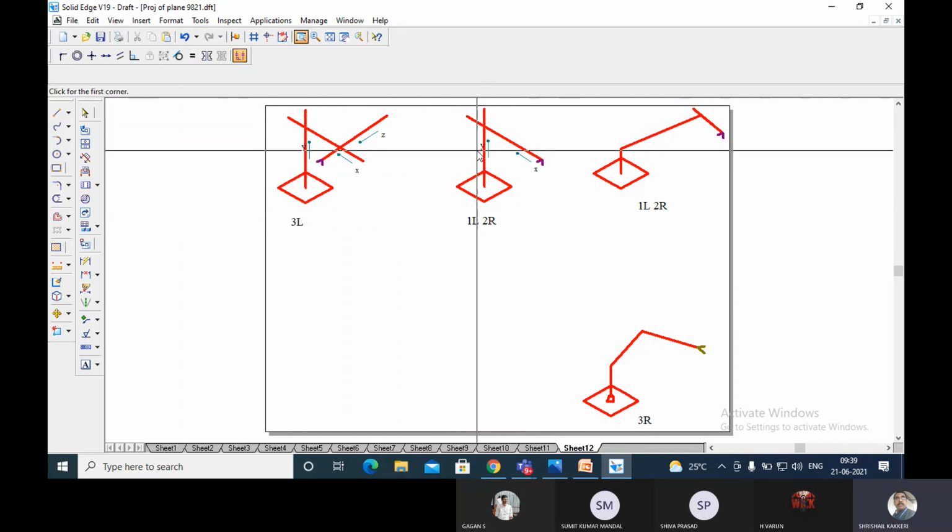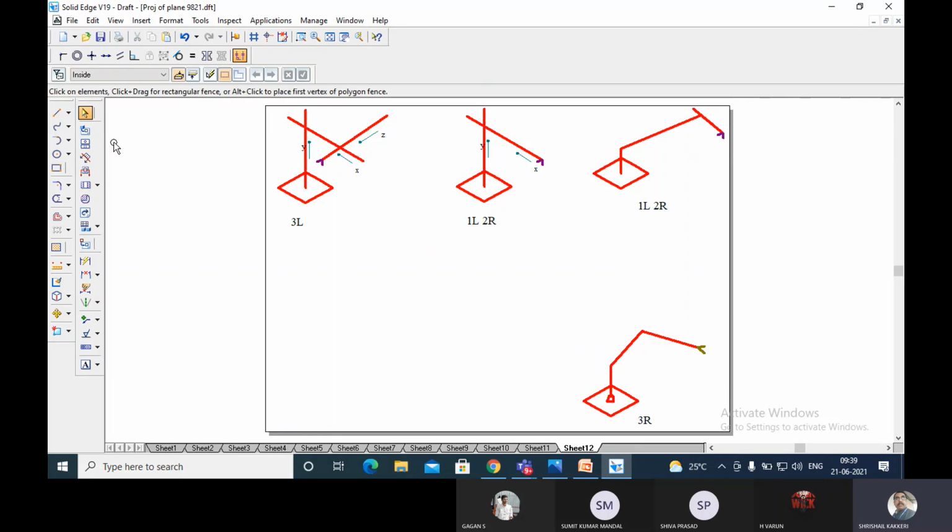And mechanical stability will be lesser compared to this one, because one rotation joint is added. So to compensate for that, we use a better controller, and this can perform pick and place. This can also do pick and place along with simple welding and spraying operations. And let us come to this. It will be spherical, or a segment of a sphere, and the mechanical stability will not be as good as these two. So it requires a little better controller, because two rotational joints are added.